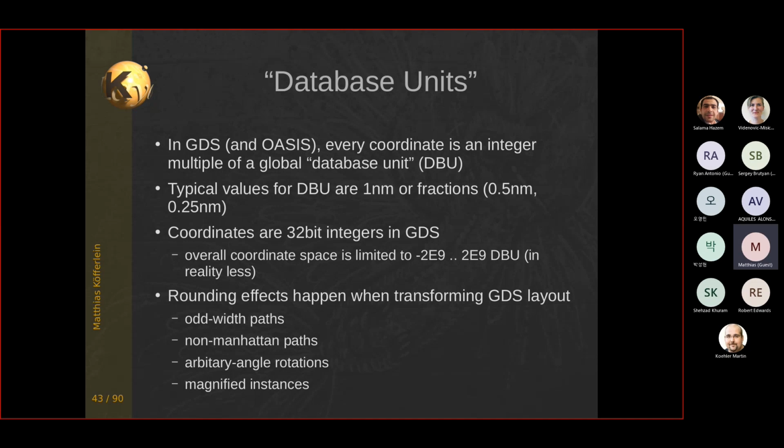Yeah. I mean, then your gate is like 180 pixels wide or units wide. That's still okay. If you want to have a grid by drawing, then you use the grid settings I've shown you. You don't need to change the database unit. Okay. It's just an internal attribute or internal parameter. Grid setting and this database unit go hand in hand. Yeah, I mean, not really. Okay, a grid has to be a multiple of the database unit. If you want to have a grid of let's say 5.5 nanometer, and you have a 1 nanometer database unit, that won't work.